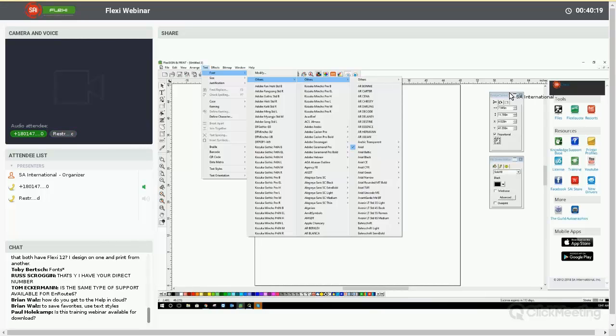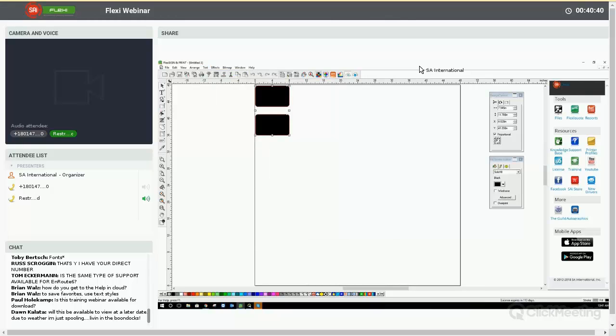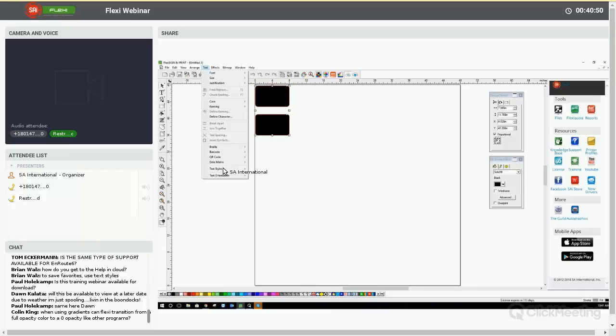Okay. Brian also commented, he said to save favorites, use text styles. Yes, text style is one option. And text styles is a little bit different lecture. I think we already covered that. If you go to our YouTube channel, you'll be able to find it. But with text styles, if you have, for example, 10 different text styles, sizes and fonts that you use, you can save them, and every time you type, you can go to your text styles and apply those to smart objects.